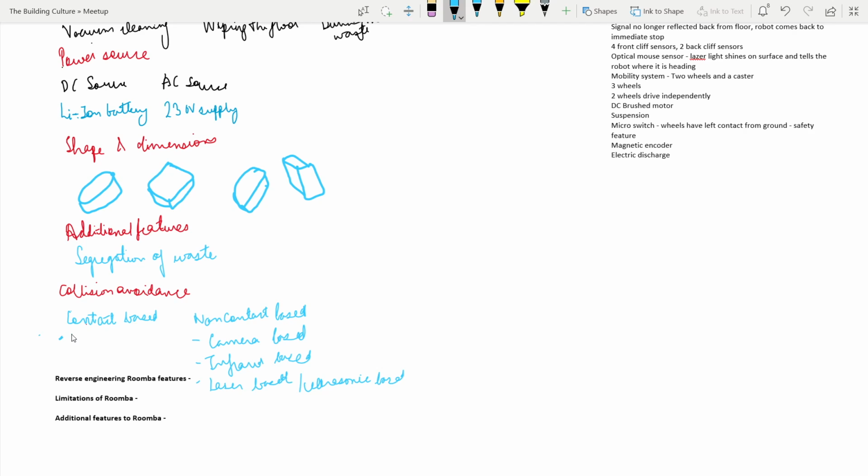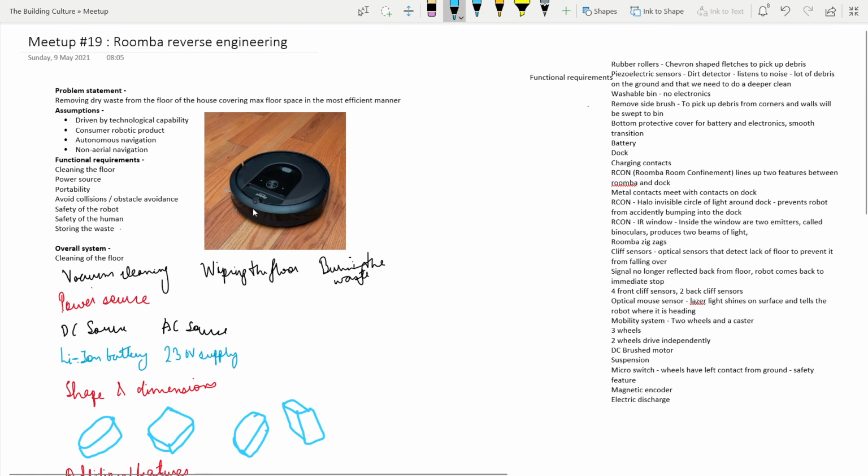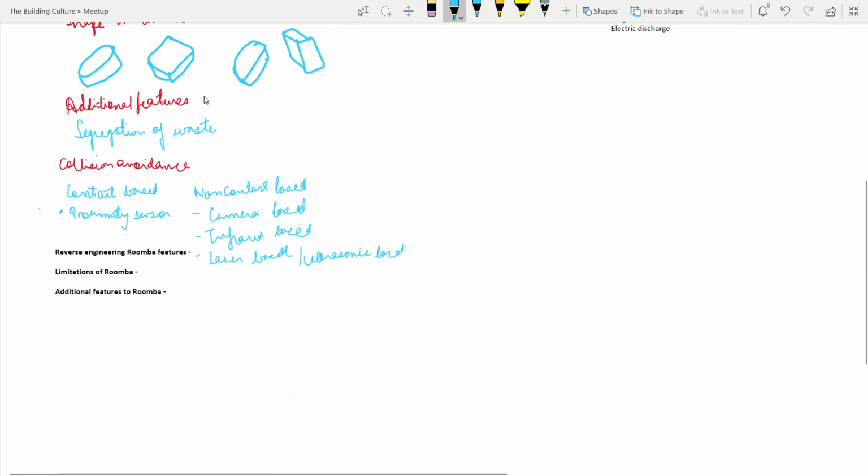No, in a bumper, how Roomba works is basically a different concept. It has a proximity sensor inside. So when the bumper touches, the proximity decreases. It knows, okay, it touched something. So there are two things that we can do. One is proximity sensor based, and the other would be the one that I mentioned. For example, when this particular bumper is pressed, maybe hit from the side, there are two or three buttons inside, and those buttons also get pressed. So that's how it knows from where it is hit. I mean, there are multiple ways, not just this way.